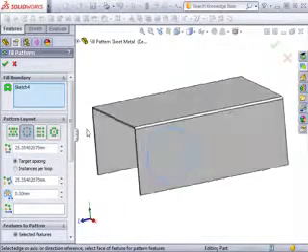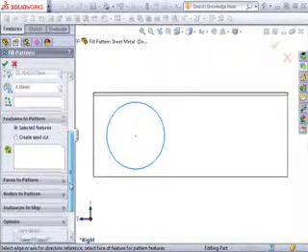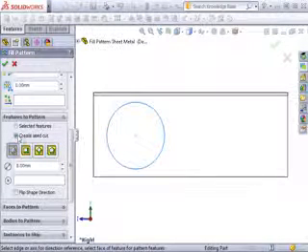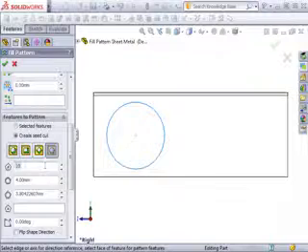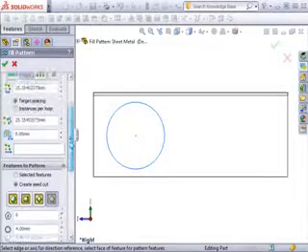Before specifying the parameters for the pattern, let's take a look at the shape I'll be patterning. You'll find 4 shapes here in the Shapes to Pattern section. I'll select a polygon with 6 sides and a 4 mm outer radius. Now that I know the size of the shape I'll be working with, I can make better decisions about the rest of the pattern parameters. I'll set the spacing to 9 mm.